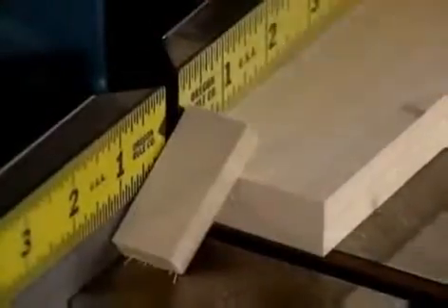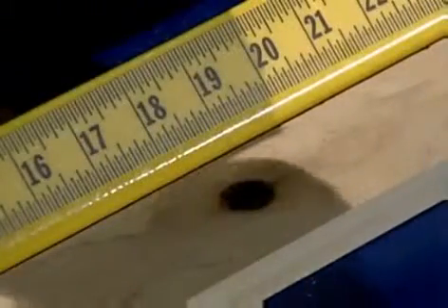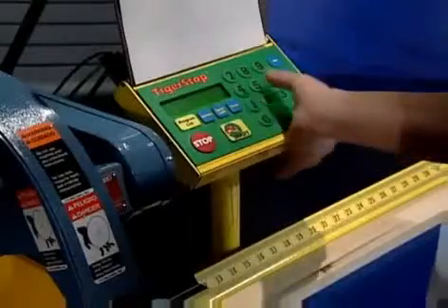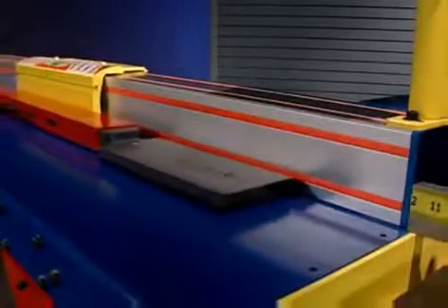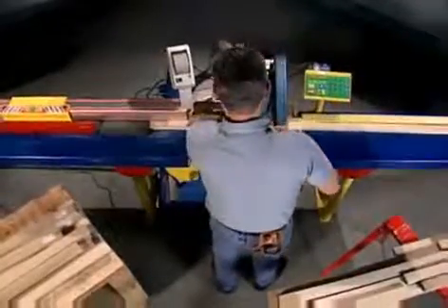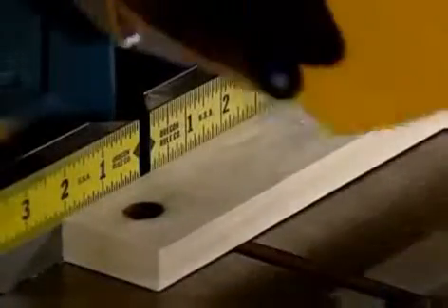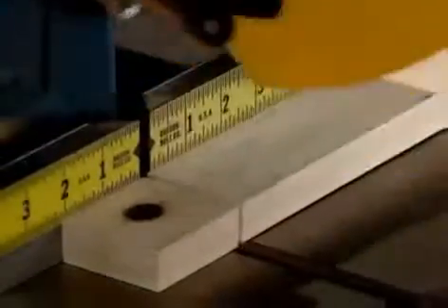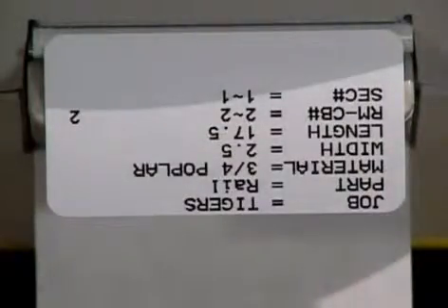Ed's made a trim cut at the beginning of the board. The usable length between the trim and the first defect is 18 inches. Ed enters this length into the controller, and the Optimizer will now look for the right combination of parts to make from the cut list. The Tigerstop Optimizer is unparalleled in processing capability, able to effectively consider up to 15,000 different combinations a second for each usable length. While Ed is cutting, the labeler creates a unique label for each piece.